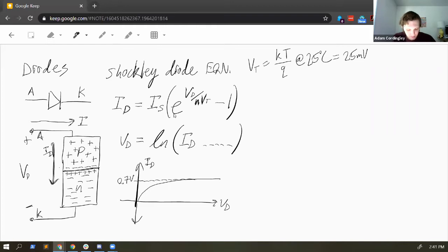The current is going to vary depending on your diode, so it's not useful to really talk about. But what I'm getting at is that for very small currents, the forward voltage can be very small. But as the current gets larger, it starts approaching, and exceeding, this more nominal forward voltage of about 0.7 volts for your garden variety silicon diode.